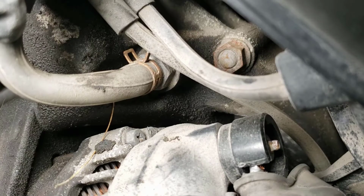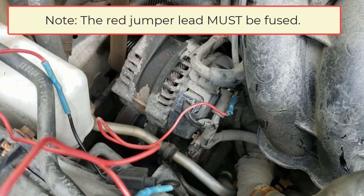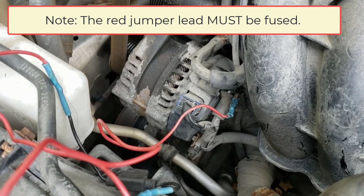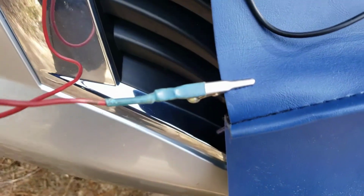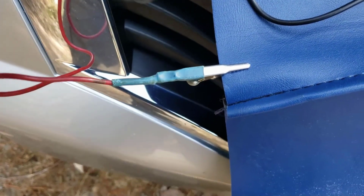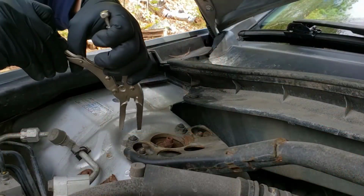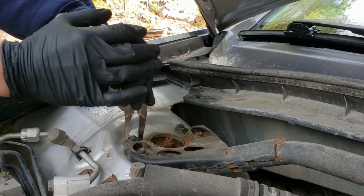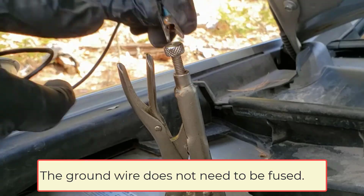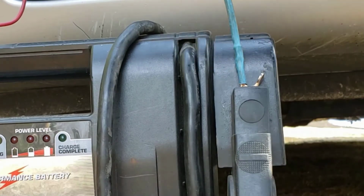So here's the alternator's BAT or B nut. We're going to attach a red jumper lead to that. The other end of my red jumper lead is going to be attached to my fender cover. I'm going to remove that, and I'm going to put that onto an external power source. In this case, I'm using a jump pack that's on the ground. I'm going to connect a vice grip to a chassis ground. I'm going to snap another jumper wire onto that and connect it to the negative side of my jump pack.